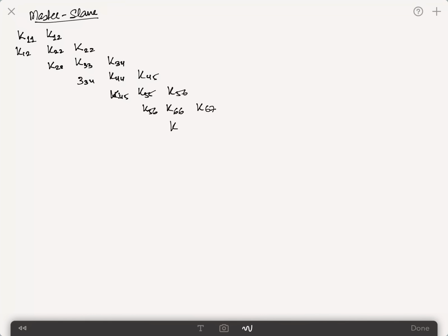Okay, now suppose we have a multi-point constraint where u2 moves the same as u6. If I want to write it in the form of a multi-point constraint equation, it's u2 minus u6. And this basically represents nothing but a rigid link, just as the one I showed you before. So if u2 moves in a certain direction with a certain magnitude, u6 will actually follow it. So it just follows.